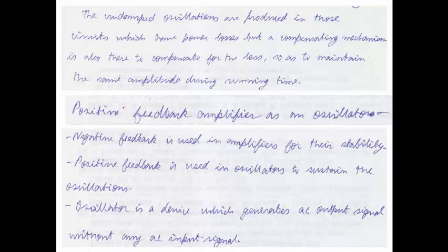However, while sustaining, we must keep in mind that although we have decided the frequency, the sustenance will always be possible only when we supply enough energy at the input of the oscillator, so that the oscillations will be maintained at the same amplitude. Now, as we very well know, oscillations can only be produced by amplifying the small undesired signals, which are called noise signals.